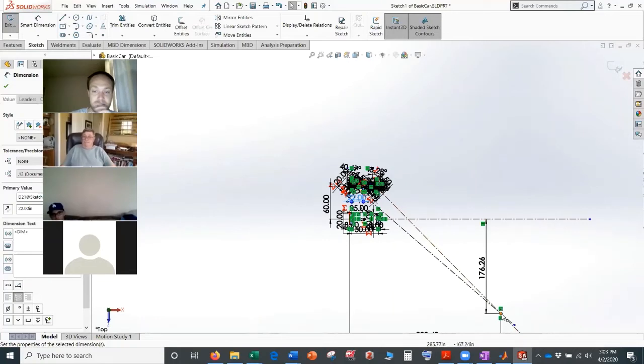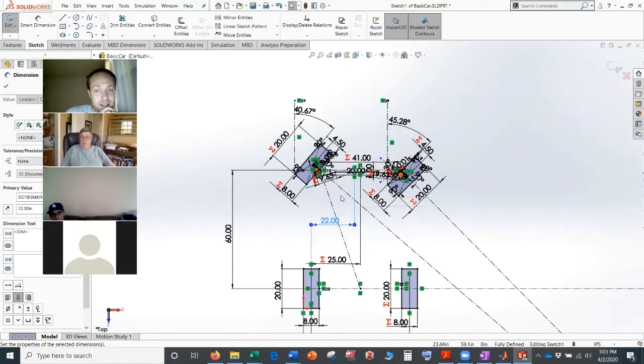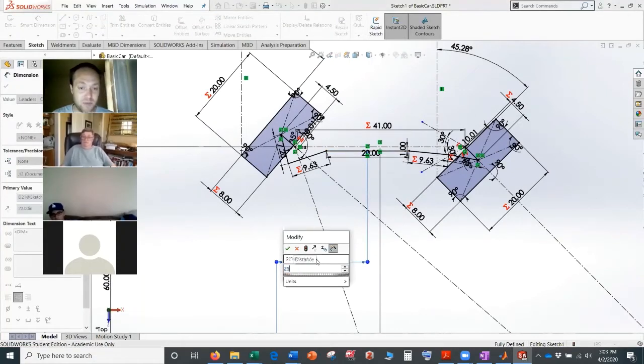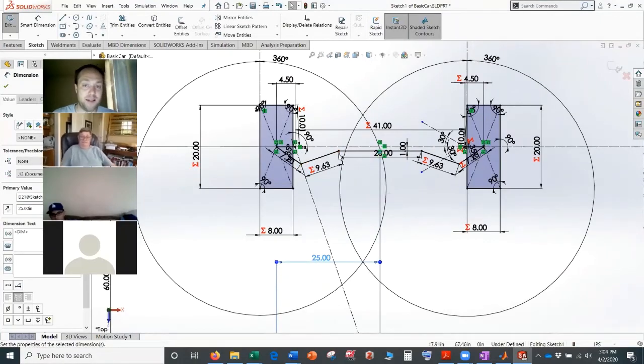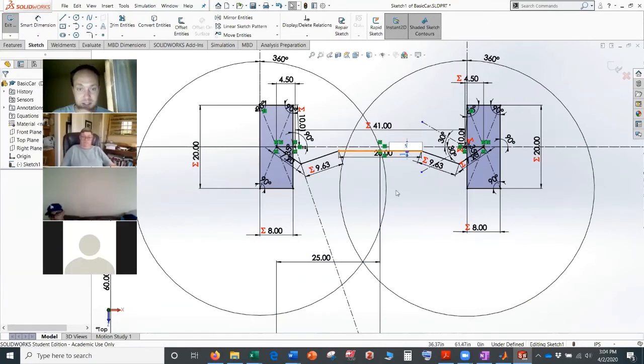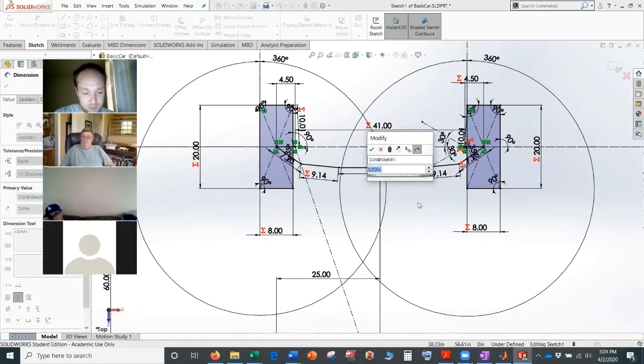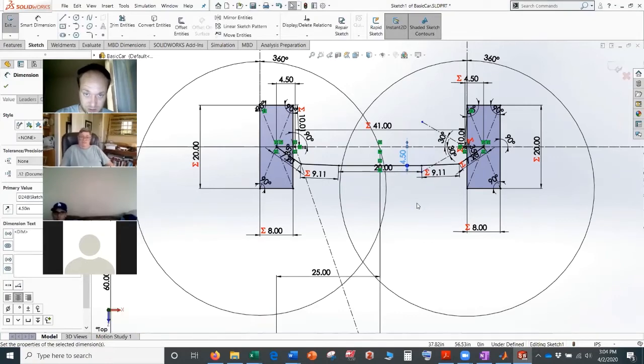So now you can see where our tires meet. It meets way back here. So we predict to have Ackermann, right? But because the rack position actually does matter, you don't just assume that because you got this meeting point right, that everything else is right. That assumes that your rack is actually, so it would maybe be like 4.5. Your rack is actually kind of in line with this, and this moves as a bar, right? And you should also keep that in mind.